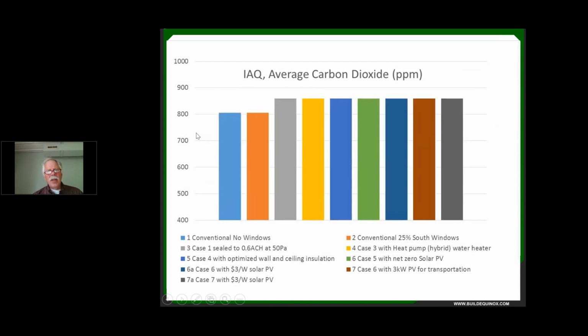On indoor air quality, as ZEROs allows you to view this, there's not much exciting going on among these different cases, because for the leaky case, I intentionally picked 7 air changes per hour. 6 to 7 is about what we're seeing a number of contractors hit without any effort towards sealing a home up with today's construction practices. And with 3 people in a house, that is roughly the boundary where, on average, the indoor air quality would be, based on carbon dioxide, something less than 900 parts per million in the home.